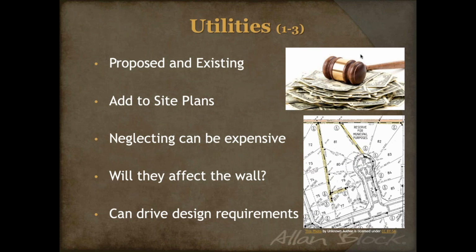Another important thing to note about utilities is that any existing or proposed utilities can drive buried block and reinforcement requirements that are going to need to be designed as part of the wall. So we like to be aware of that, so that moving forward with the design, we know if we have to make any special arrangements for those utilities.